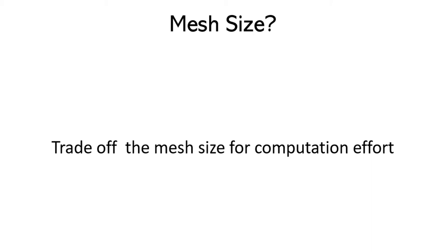But if it is semi-rigid, then every node created from that meshing would carry its own degrees of freedom. So if you're considering the rigid diaphragm, the program is going to run the model much faster compared to the semi-rigid one. Now, when you are using the semi-rigid one, the question comes: what mesh size do we take? Because you need to decide the trade-off in considering the mesh size.